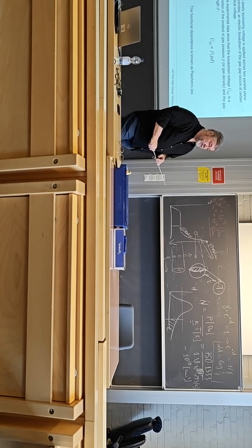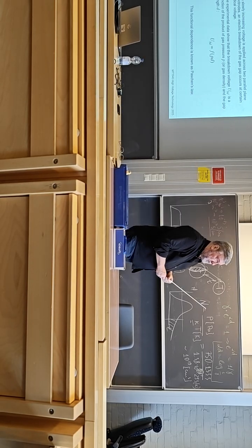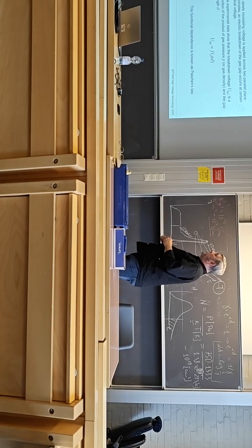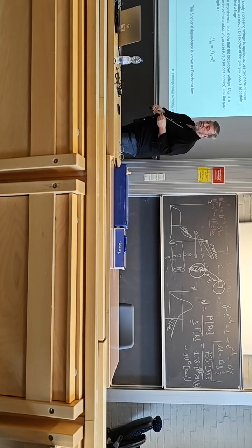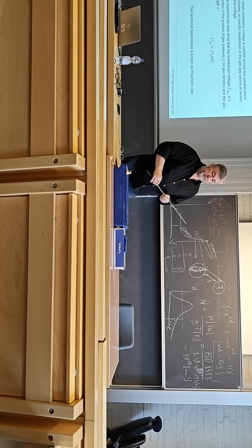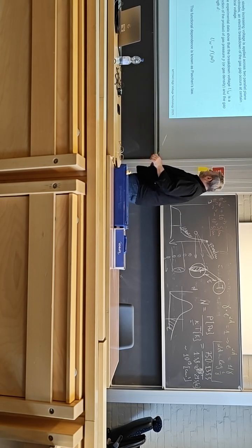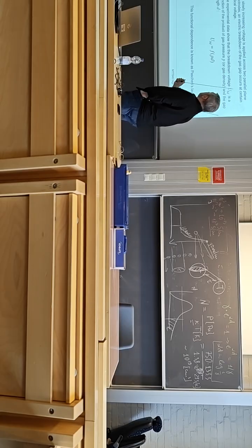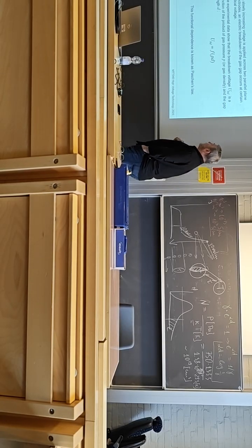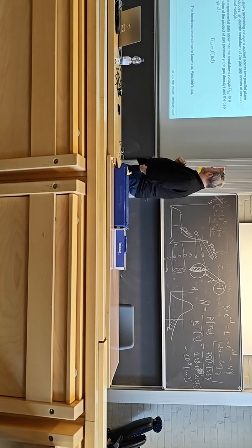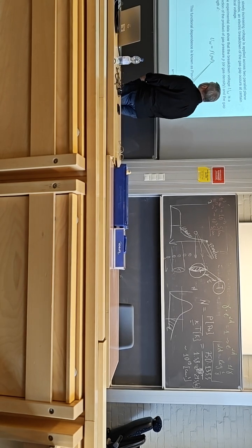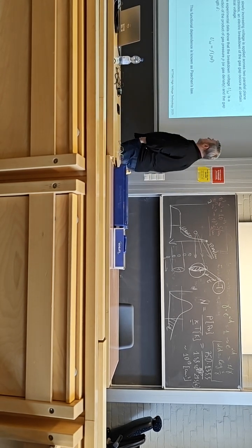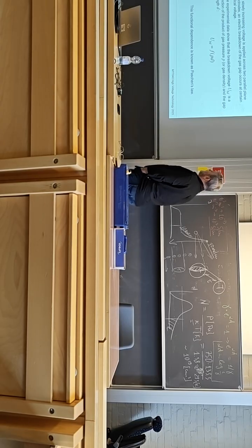Paschen's law, what is this? This is a kind of similarity law which shows that breakdown voltages in the uniform field between parallel plates are functions of this product, pressure and the distance between the electrodes.